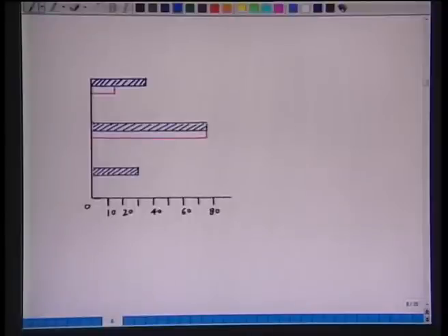If I do not want this highly penetrating jet, I remove the natural gas. So, the jet will behave in a similar way as in the previous cases. What I have illustrated from here is that a jet surrounded by a flame has a higher potential core, and such a high potential core penetrates deep into the bath and can meet the requirement of the oxidation reaction. So, now I can show here, for example, the nozzle diameters.